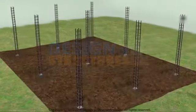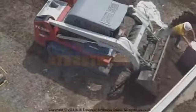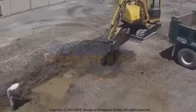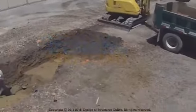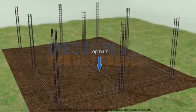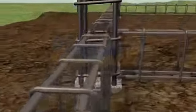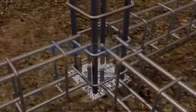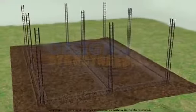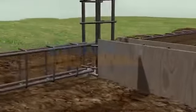Backfilling. Once the foundation is completed, backfill the remaining excavated area around the foundation with soil. Backfill provides stability to the building. Plinth beam as foundation. Beam reinforcement shall be as per drawings. Top bars, bottom bars and stirrups to be placed with proper development length. Joints in the beam shuttering should be tight against leakage of cement grout. Construction of shuttering should permit removal of various parts in desired sequences without damage to the concrete.